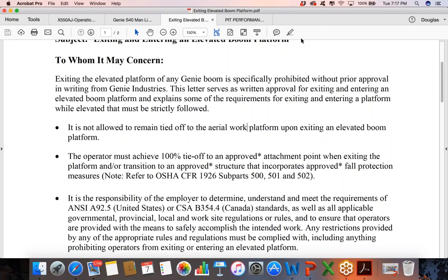The same rules apply for all forms of threats. It could be keeping a watch in all directions, especially overhead when we're working around cranes. It could be if a machine is nearby operating, we want to make sure that we're not going to become a hazard to the machine and we won't harm that machine where the machine may harm us in turn. We want to be cautious of any type of equipment that's in a kinetic state, basically in movement, like a spinning wheel or some type of drum that might catch the sleeve or the pants of an employee.